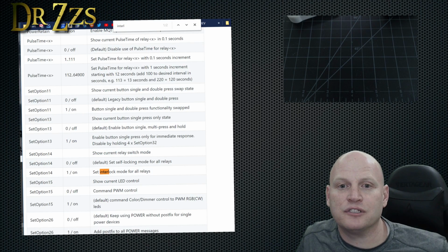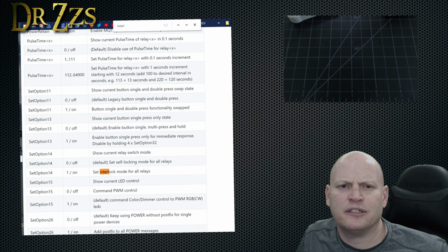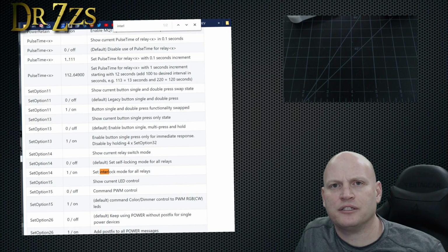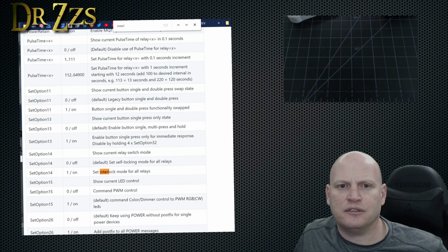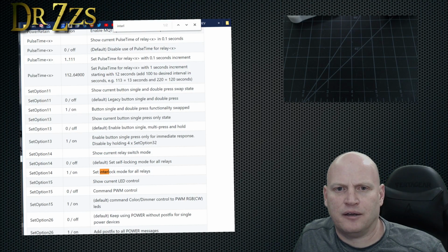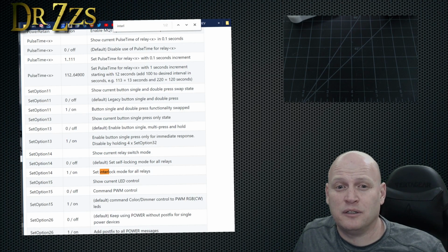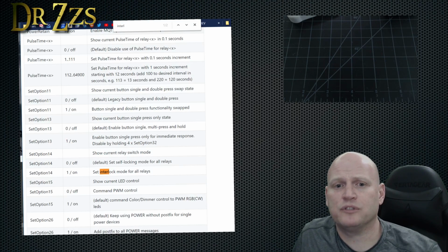PIR sensor toggles in the console. It just says toggle, no on and off. Don't think it's correct. It needs power on and off, right? Yeah, it should. So tell us, Demps, I think you've asked me this question on email or something too, so I'm sorry I haven't gotten back to you. I'm bad about that, obviously. It's hard. So tell us what PIR sensor, where are you using it? Is it just connected to a D1, like a D1 Mini or NodeMCU? Is it connected to a Sonoff? Is it an RF thing? And then in the console you're talking about in Tasmota, so this must be something with an 8266. Give us more information and we'll help you solve it.